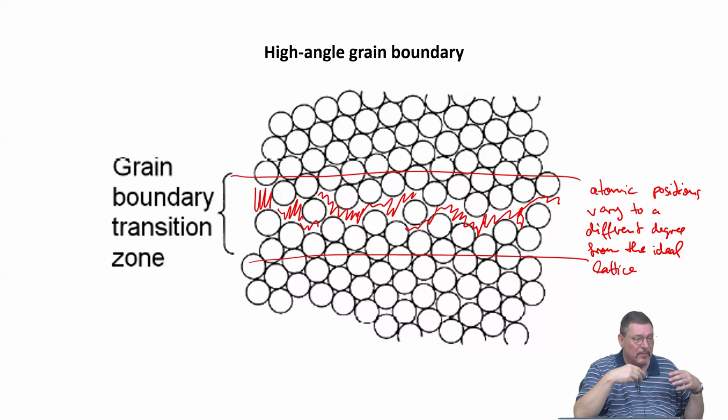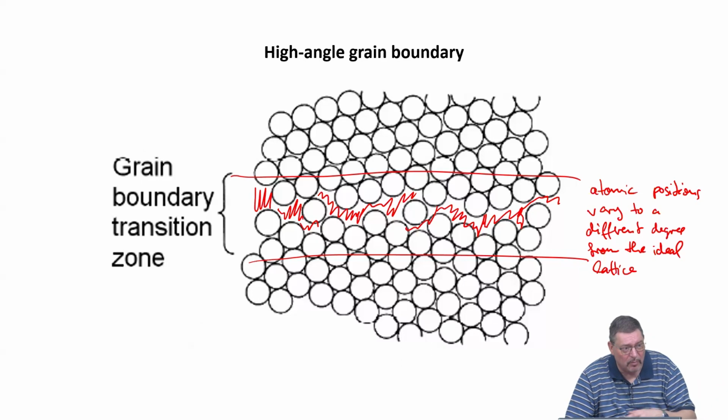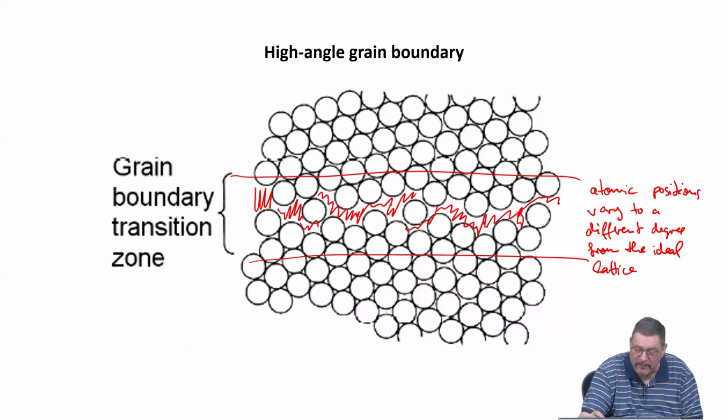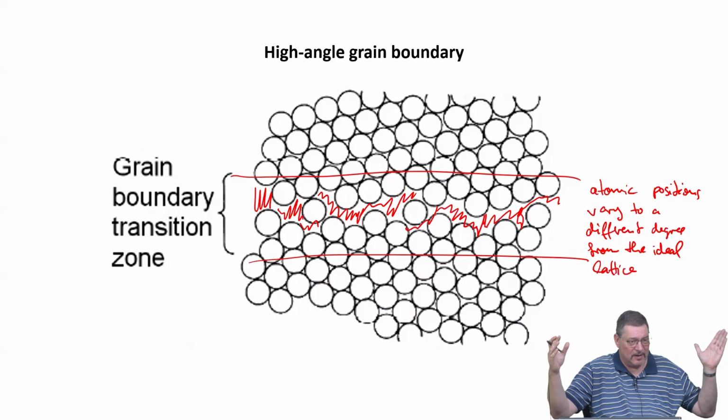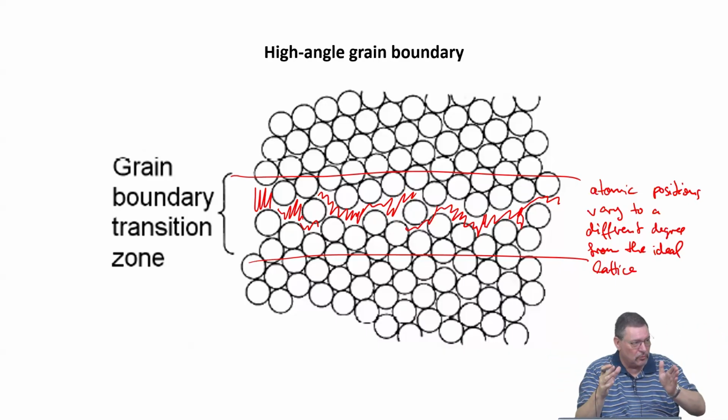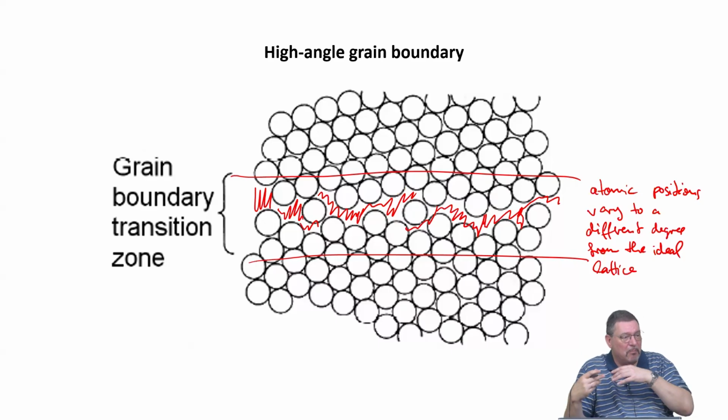They also become excess volume. And this is the important point here. Right? So this has too much excess volume. You can almost fit an atom inside of these gaps. So this is really just a coarse-grained, rigid point of view of cutting two crystals. You have atomically rough surfaces, you bring them together and you see, in some cases you have good registry, less excess volume. In some cases you have bad registry, high excess volume.